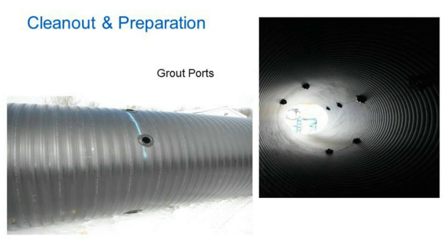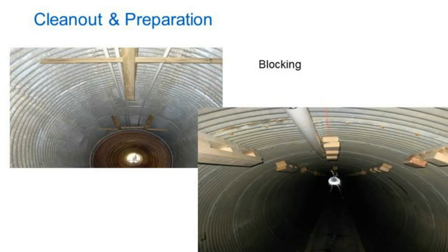As with rails, and when possible, blocking should be placed prior to placing the pipe to resist buoyancy during grouting and keep the pipe on grade. Here you can see a couple of different forms of blocking techniques.